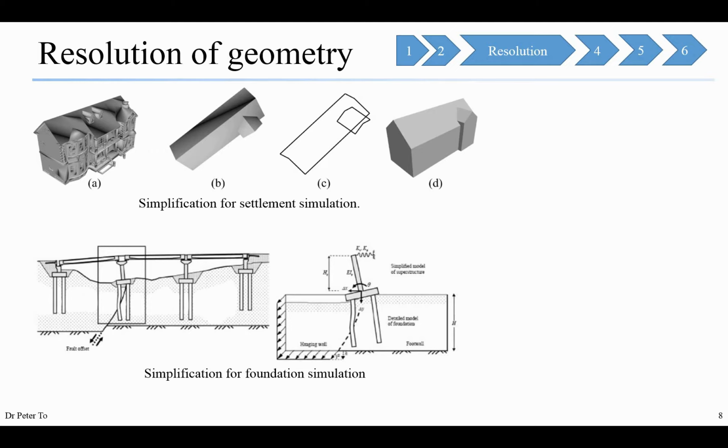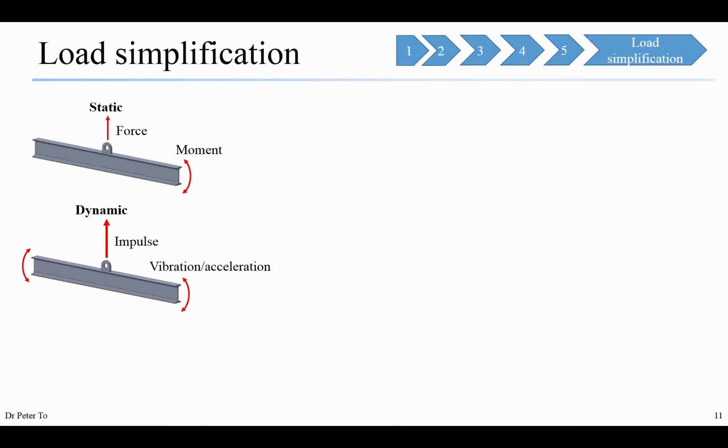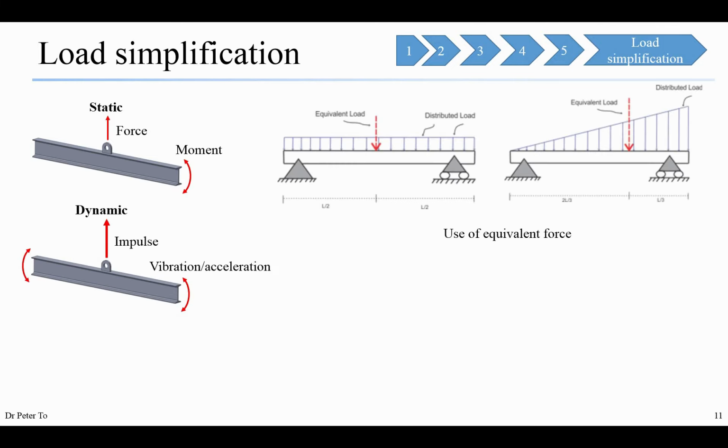In the last step, about load simplification, we try to study the static and dynamic loads, and we have to simplify them into nodal forces. Please remember that in the original finite element method, we don't have a force acting on an edge or area. We have the force acting on the nodes only. So therefore, we have to simplify it to an equivalent force.